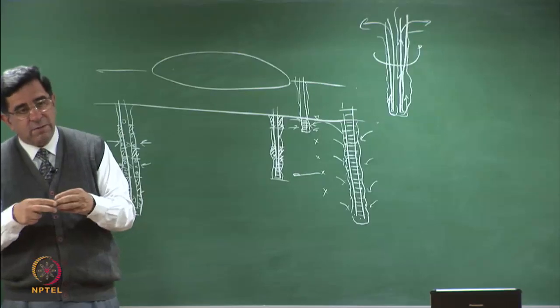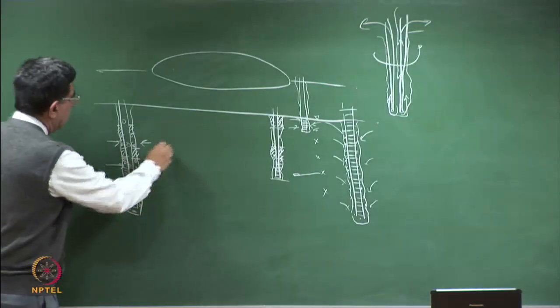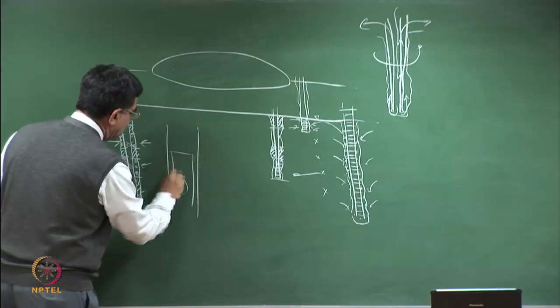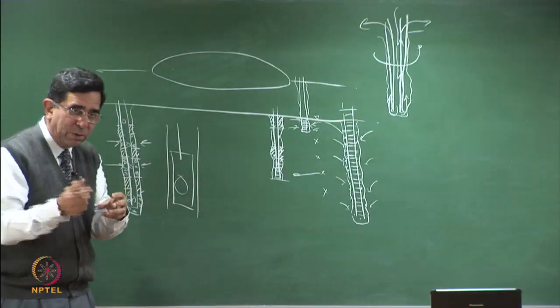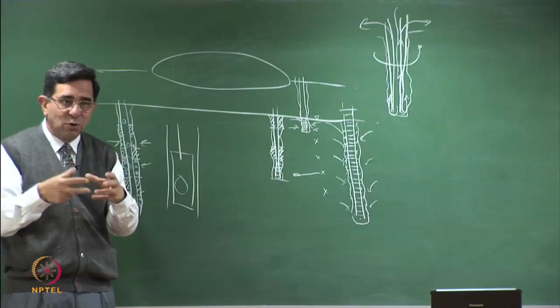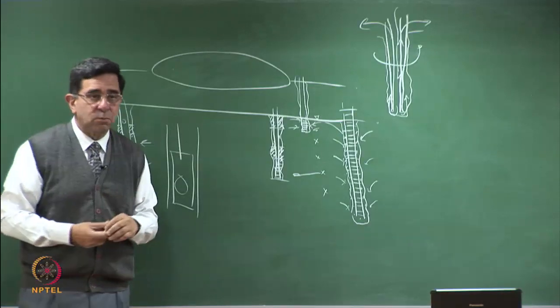Then finally dock it and take the sample. If this is the pipe and this is the port and a sampling device is coming down and docking itself, it means it attaches itself and you can open the dock, then you are only picking up water from that zone which is coming in from here. Okay? That's what a multi-port device is.